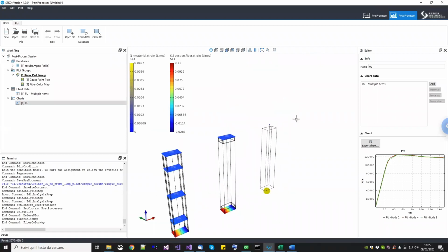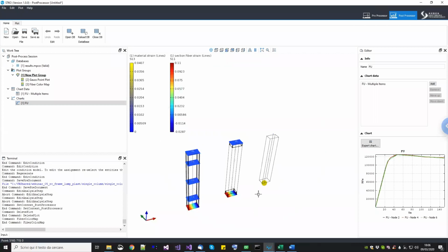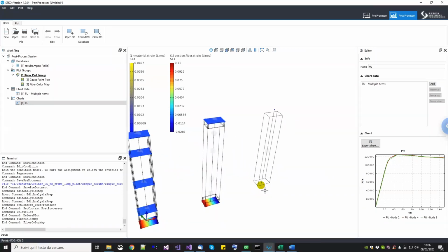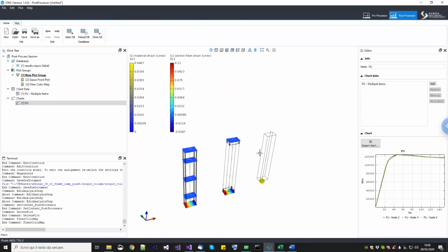And then there is the most common one, which instead is an elastic beam with 2 zero-length springs at the 2 ends of the beam. This one doesn't use any fiber cross-section. It uses a phenomenological constitutive model for each one of the directions, so there is no coupling between the bending responses in the 2 directions, and there is no coupling between the bending response and the axial load.